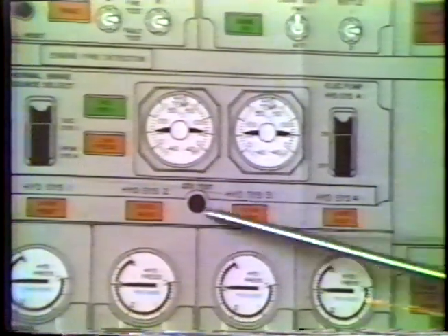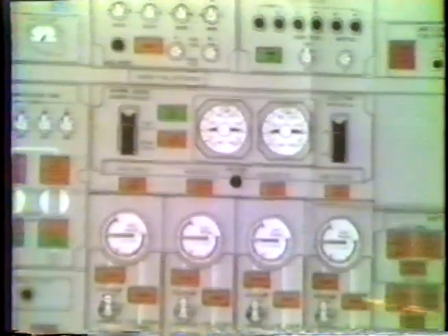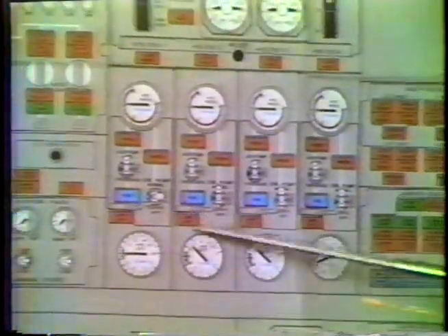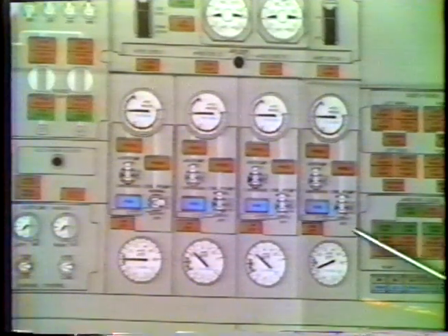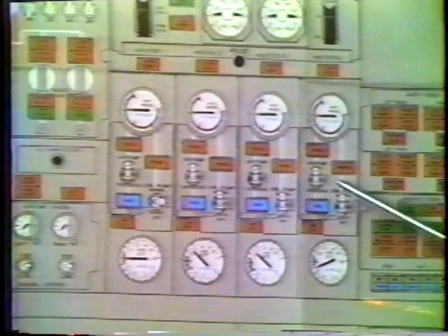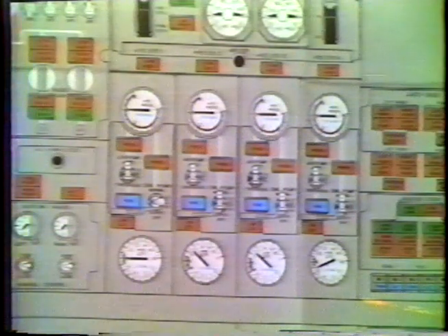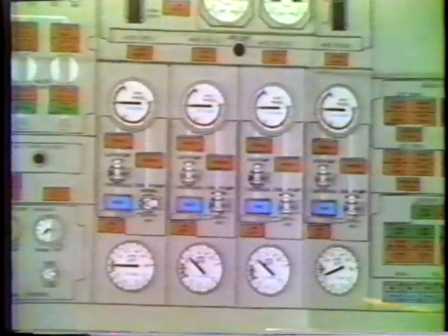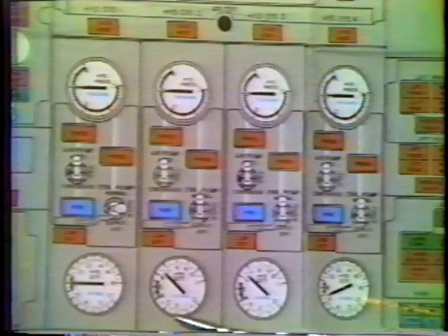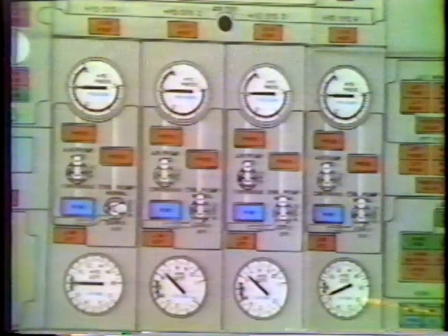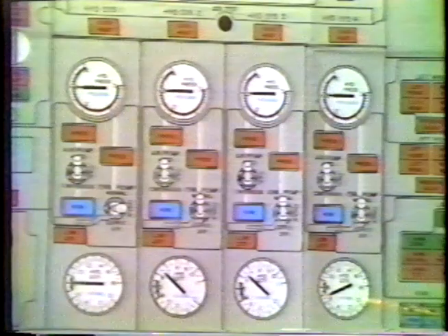Quantity test. When you push the quantity test gauge, you drive the gauges towards 0. When the pointer gets around the 6 o'clock position, the low quantity light will come on. One of the problems you should be aware of on this is the quantity test. All 4 quantity gauges are on one circuit breaker, and if that should pop, the gauges freeze in position. However, subsequently, if you should lose quantity out of the hydraulic tank, the low quantity light will still come on when the quantity gets down to the actual value of the 6 o'clock position.